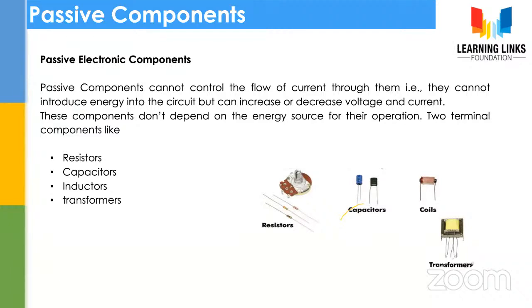It is a passive two-terminal electrical component that stores energy in a magnetic field when electrical current flows through it. When we provide electrical energy and increase the flow of current through this coil, we develop a magnetic field. That's why we say this electrical component stores energy in a magnetic field.